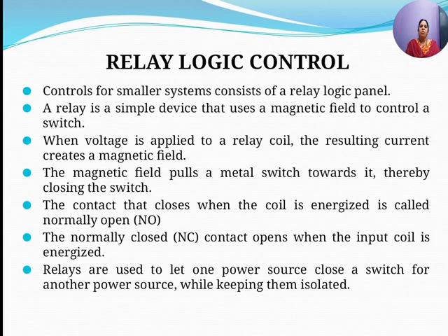The contact that closes when the coil is energized is called a normally open contact, NO. And a normally closed contact opens when the input coil is energized. Why are we using relays? Relays are used to let one power source close a switch for another power source.